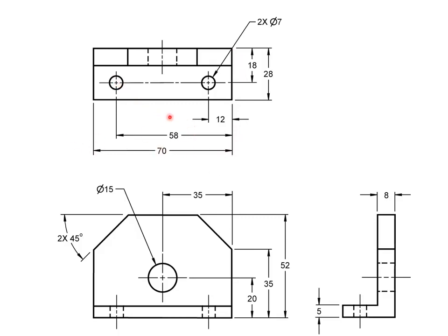Notice here we didn't use continuous dimensioning. Instead of the 58, we could have used continuous dimensioning. So take 58, subtract 12, that'll give us 46. Now we could have used 46 instead of the 58, but since the 46 was not used, that tells us that the hole pattern is on its own. It doesn't mate up to another part with the same hole pattern. Okay, so here the 58 is more important than the 46, so we'll just use datum dimensioning versus continuous.